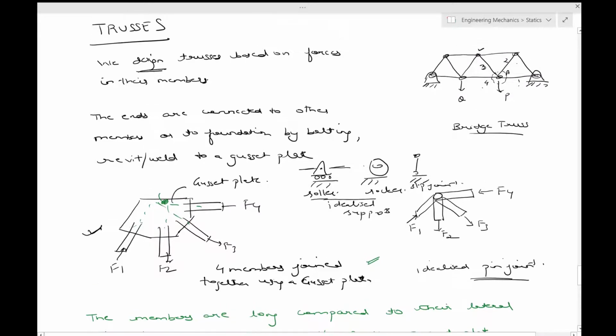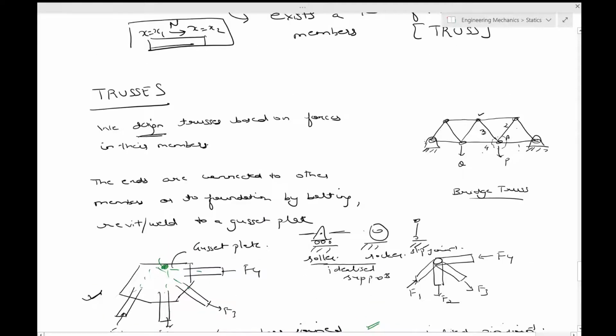So if you have, for example, a support over here like this, and because of the temperature change, you have to allow for expansion or contraction depending on whether the temperature is increasing or decreasing. That can be done by this sort of a support. If the truss does not have a provision for either of them, like roller, rocker and slip, then they are usually statically indeterminate.